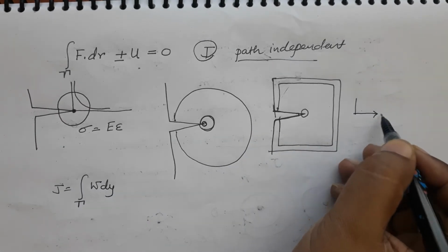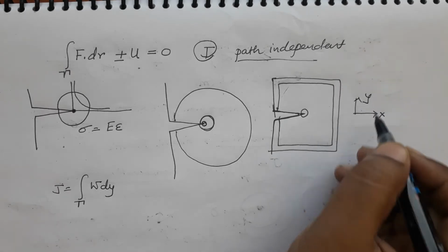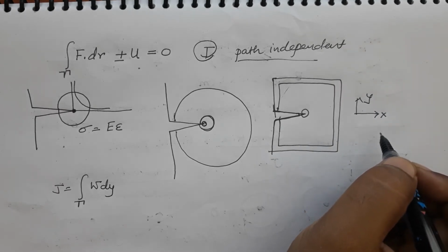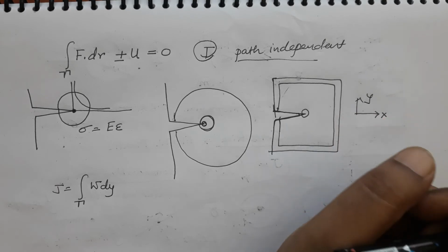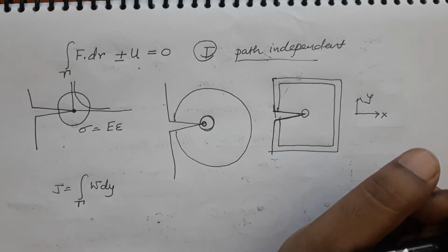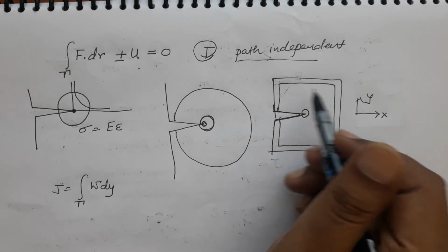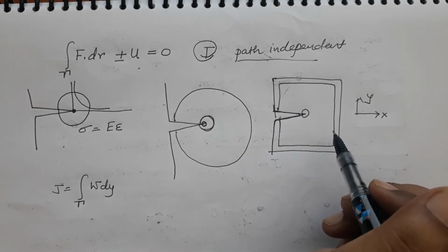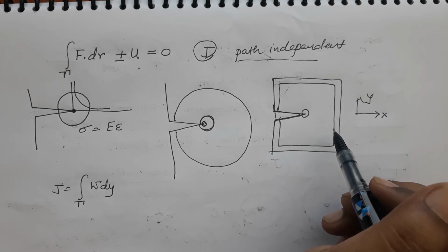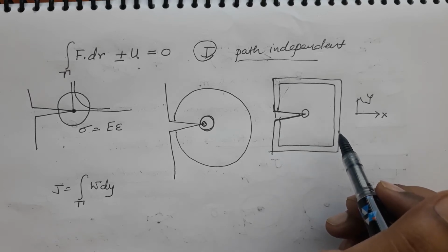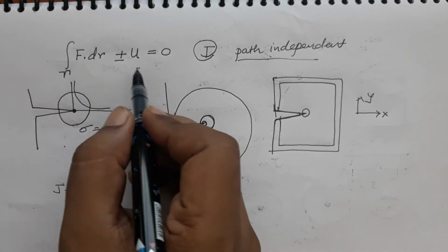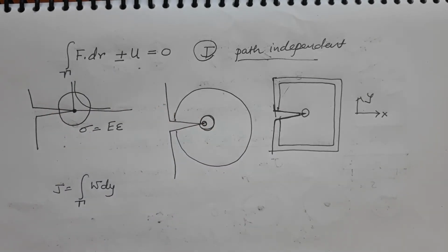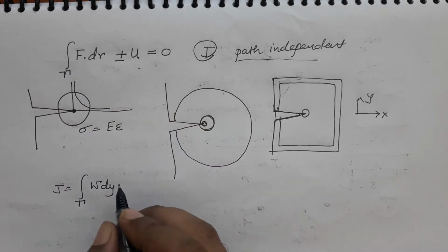So, this is x, this is y, and we are dealing in 2 dimension. This whole idea was also invented or applied because this kind of formulation already existed in other domains of energy. So, in electrical energy and in magnetic energy fields, or in any other conservational energy field, we had this kind of formulation already, which was applied by James Rice in fracture mechanics.